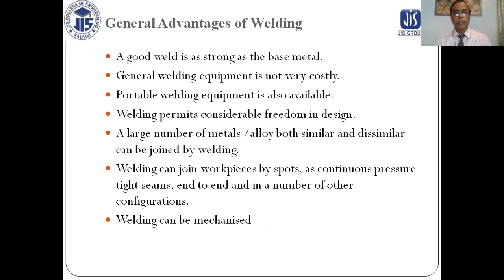General advantages of welding: a good weld is as strong as the base metal. General welding equipment is not very costly. Portable welding equipment is also available. Welding permits considerable freedom of design. A large number of metals and alloys, both similar or dissimilar, can be joined by welding. Welding can join workpieces by spot, continuous pressure type seams, end-to-end, and in a number of other configurations. Welding can be mechanized.